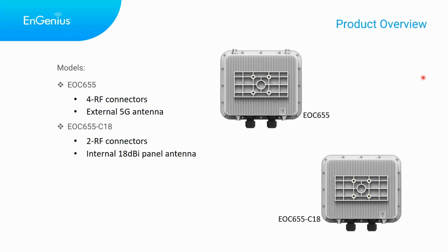But yeah, if you're asking about the controller itself and you don't want to use the SkyPoint software, you can also set up the access points by themselves or on their own. So you can set up a base station unit and then from there configure it from the local user interface, meaning from its IP address. Once you access the IP address of the unit, you'd be able to configure the system as well. If you have multiple links or multiple points, you will see that on the system.